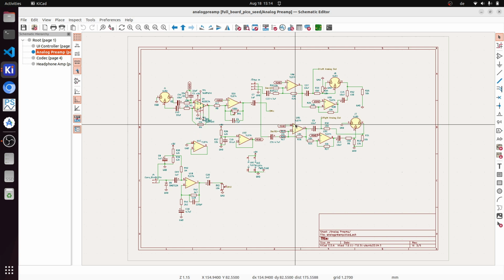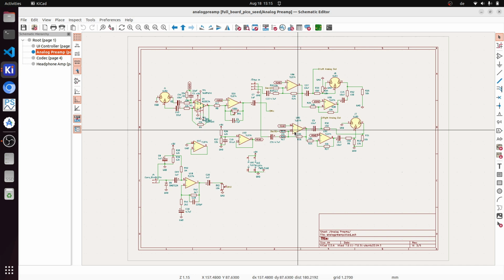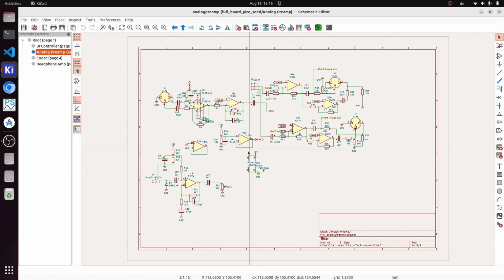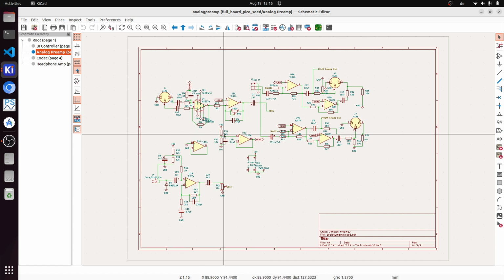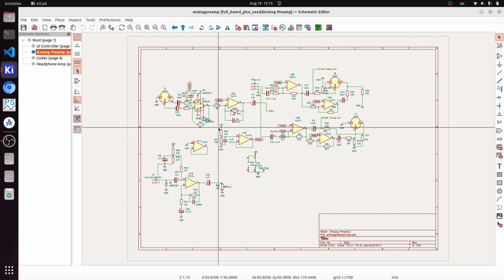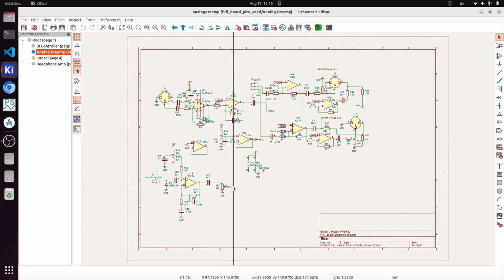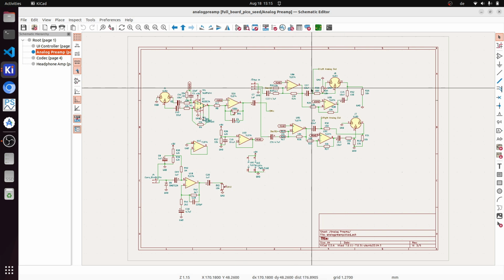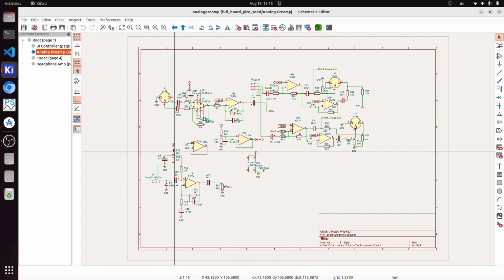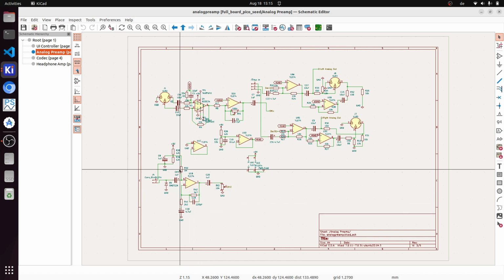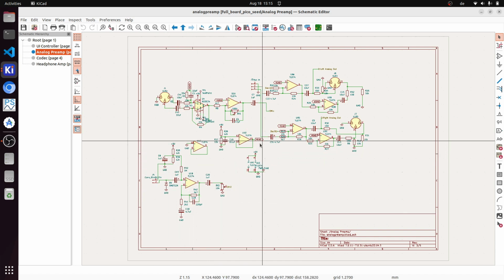By the way, the op-amps are all TL074s or 72s. And well, the analog part relies on a virtual ground, which is created using an input follower with a voltage divider. This is a major change because the first iteration worked with fully symmetric input and output voltages. And of course, what I needed to add are the coupling and decoupling capacitors. The headset part is also built around a single operational amplifier, and it uses a special virtual ground which is not shared with the others.